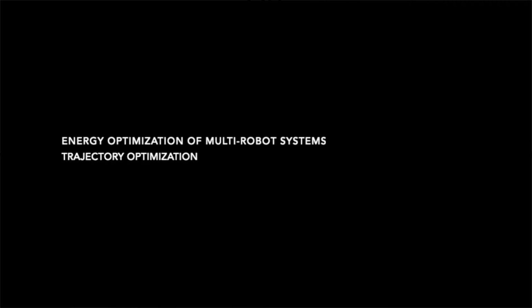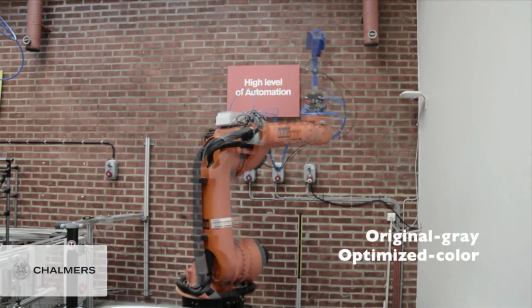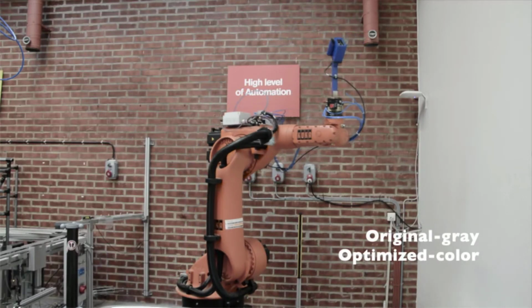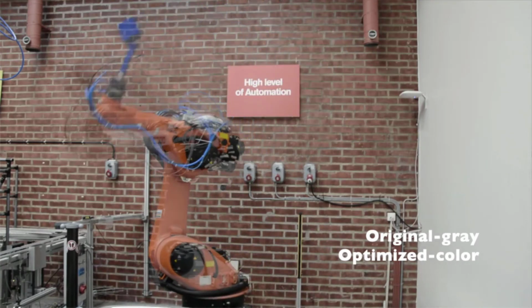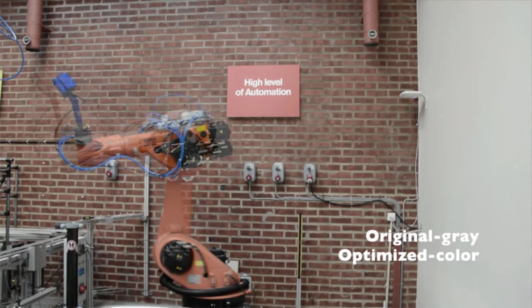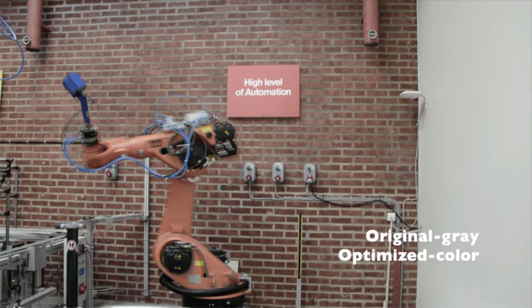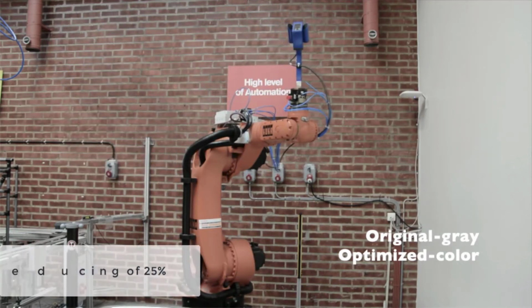The next demonstrates the possibility to optimize energy consumption of industrial robots by minimizing the acceleration and speed and scheduling of the process task sequence, keeping the same move path and target cycle time. Thanks to this, the energy consumption of the shown robot was reduced by approximately 25%.